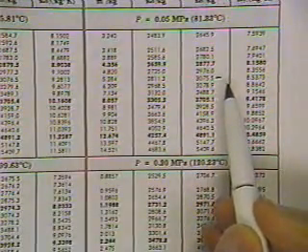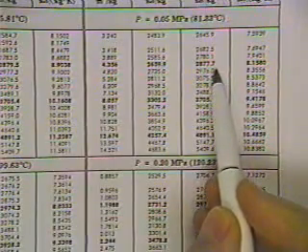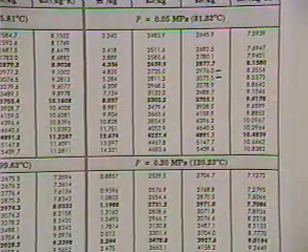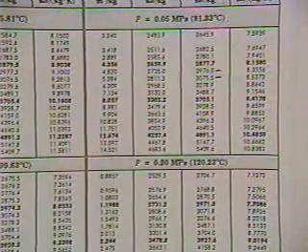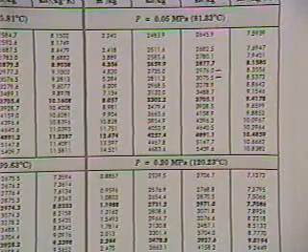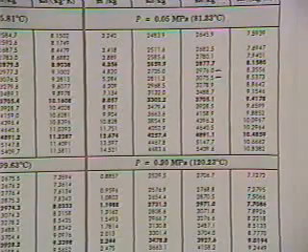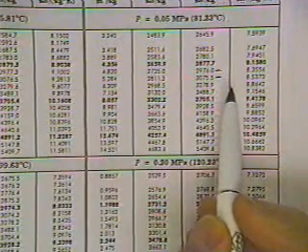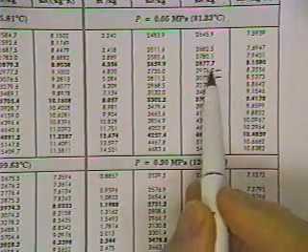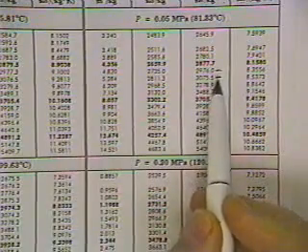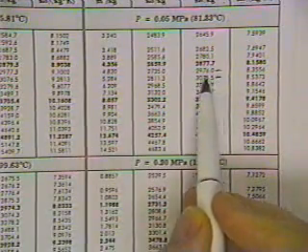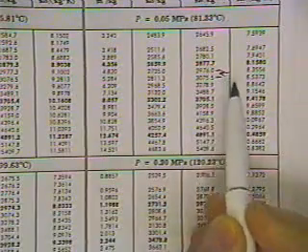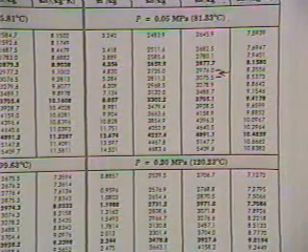so we are between a temperature of 300 degrees and a temperature of 250, and we'd expect that's where we'd start out, because our temperature doesn't drop too much as the flow goes through a nozzle. But this is an interpolation problem. We have an enthalpy of 3021.8, and the temperature is going to lie between 250 degrees centigrade and 300 degrees centigrade, and so in order to find the temperature, we've got to interpolate between those two values that are on the table.